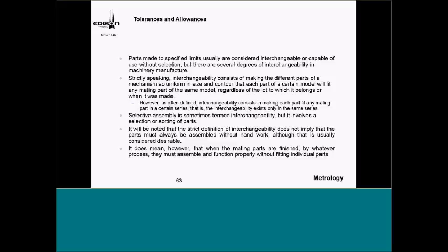Selective assembly is sometimes termed interchangeability, but it also involves the selection or sorting of parts. And again, it's desirable that if we don't have to touch anything when we end up buying it, as they said, it's noted that strict definition of interchangeability does not imply that the parts must always be assembled without handwork.